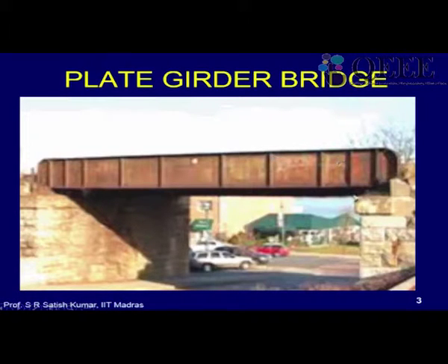So these are the stiffeners which are provided, and note that the spacing of stiffeners is large in the middle and becomes small at the ends. This is because shear is practically zero at midspan. So there is no question of shear buckling, and as I come closer to the support, the shear increases. So I'll provide closer stiffeners. Okay. So this is one way, but generally in many girders, the stiffeners are spaced at equal intervals towards the end parts of the girder, and in the middle part the spacing is varied. Okay, so that can also be done.